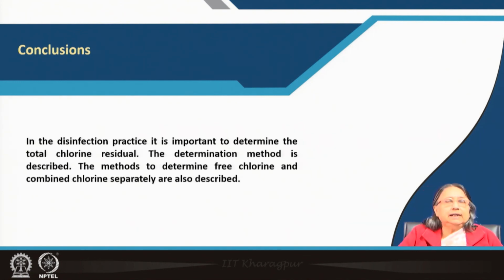And as a conclusion from this lecture: in disinfection practice, it is important to determine the total chlorine residual. The determination method is described. The methods to determine the free chlorine and combined chlorine separately are also described. There are different methods, you can choose which one you will apply.